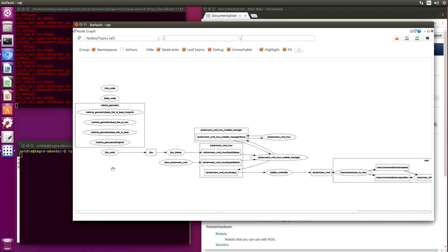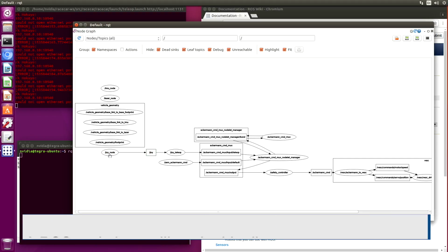The makeup of ROS is pretty simple conceptually. There are nodes. The nodes are connected. ROS is a distributed processing environment. A node is a process which performs computation. The environment can be thought of as a graph with nodes and edges. The nodes are ROS nodes. For example, we have the /joy_node.